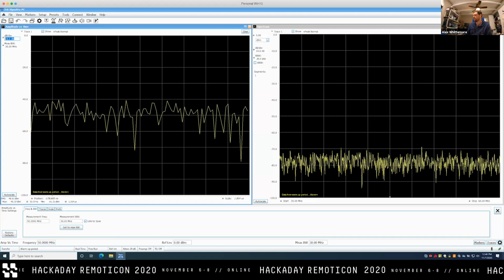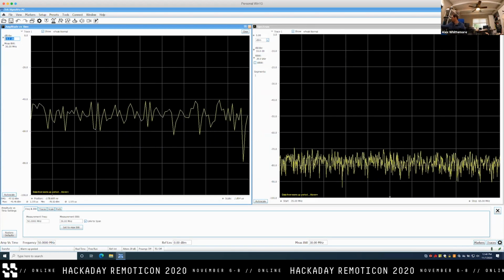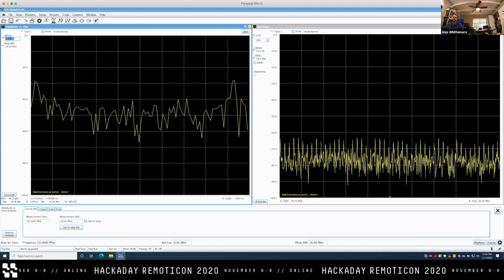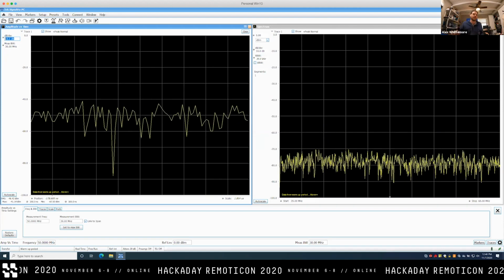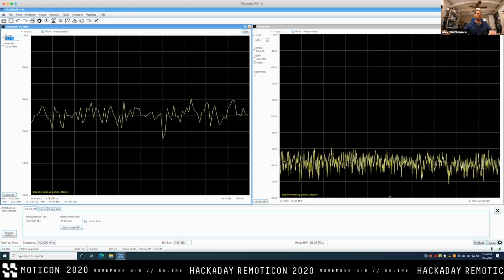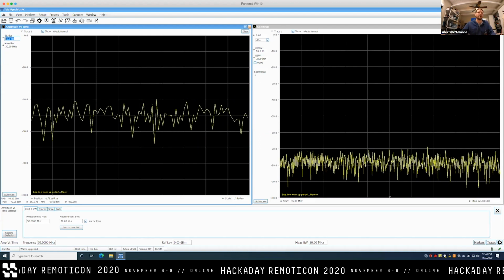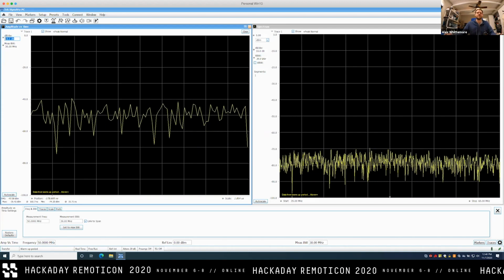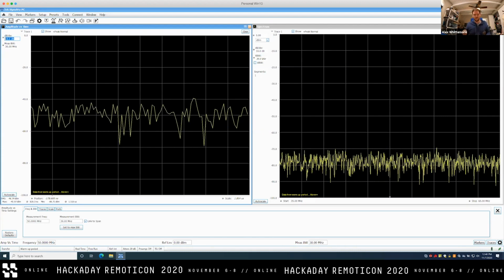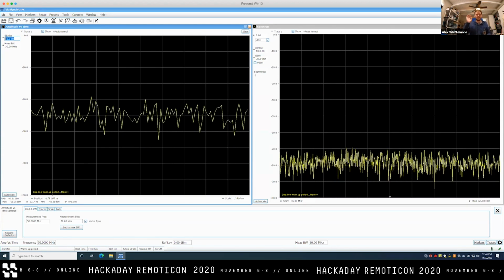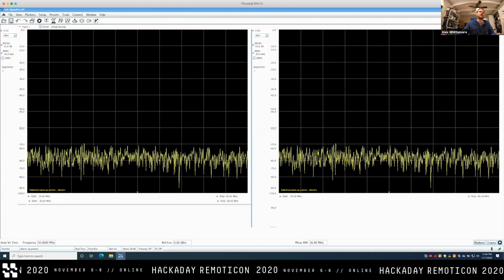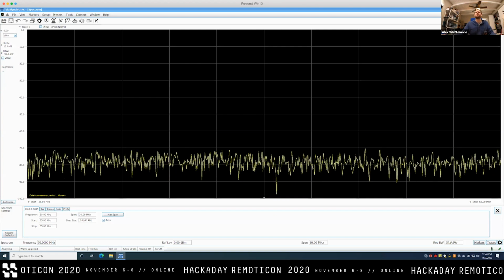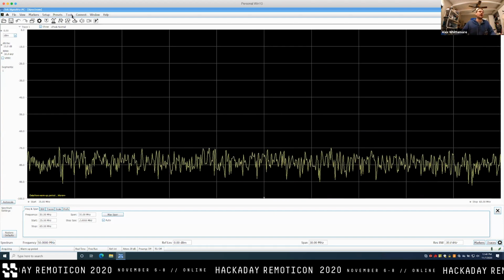I'm sure I've just got the wrong tool. When you are over a particular frequency of interest and you see the spike, it'll basically make a whistle that gets higher in frequency with higher amplitude of that section of spectrum, and lower otherwise. So that instead of having to stare at a screen while you move your probe physically around, you can listen audibly for where the signal happens to be loudest, literally. I don't want to dwell too much time on that.